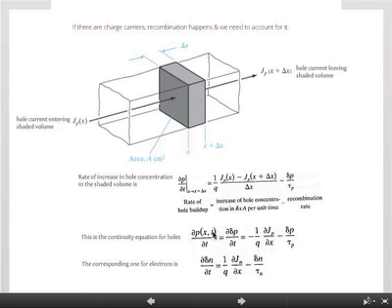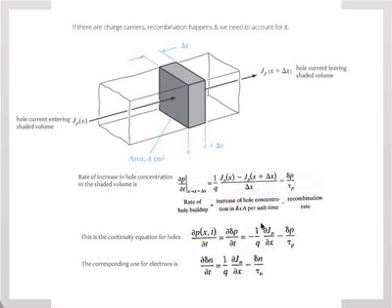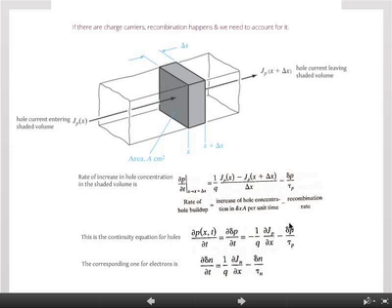And the continuity equation just says that the rate of change of holes in space and time is given by, ignore that part for the time being, the rate of change of hole current with space, which is basically how many holes are coming into an infinitesimal region, net holes coming in, so coming in minus going out, minus how much you lose by recombination, which is just that term.